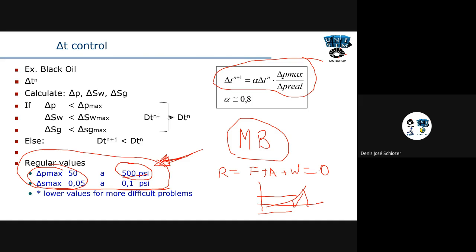We are going to converge, and this is the answer. So my residual is not exactly 0. It's something small and close to 0, but not exactly 0. So what the simulation does, it calculates the material balance, calculates the absolute value of the residual, and then it calculates all the residuals for all the time steps and adds all this.